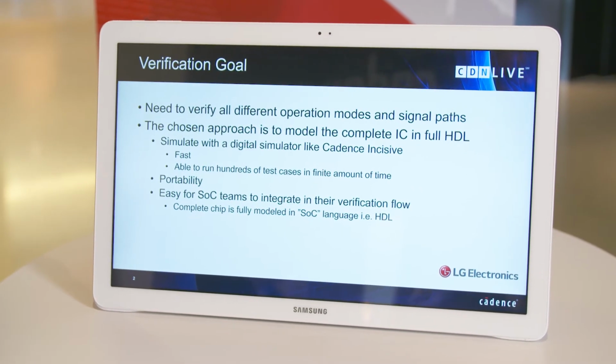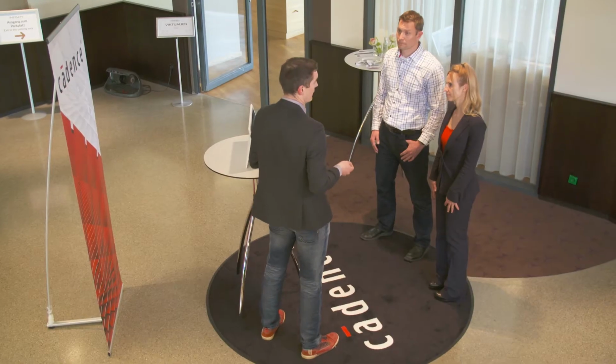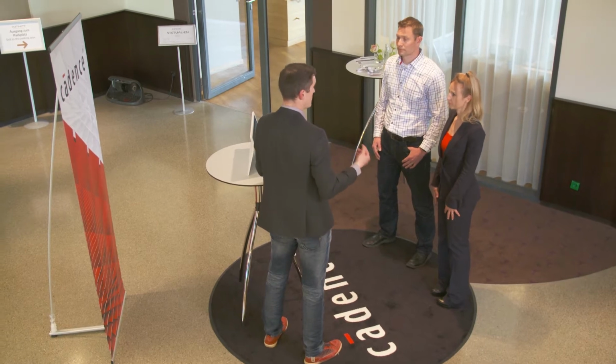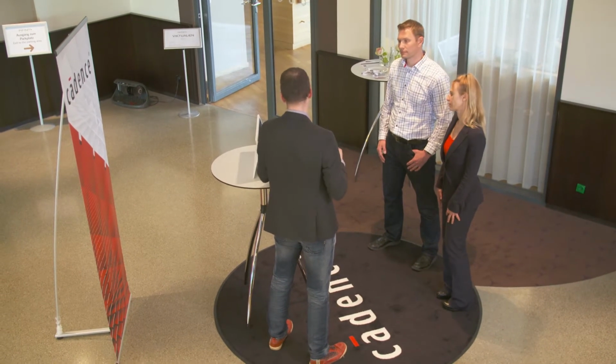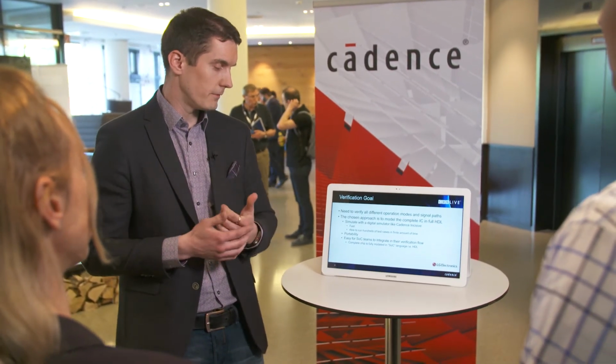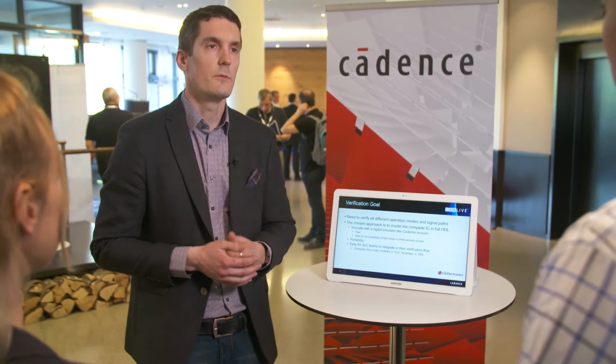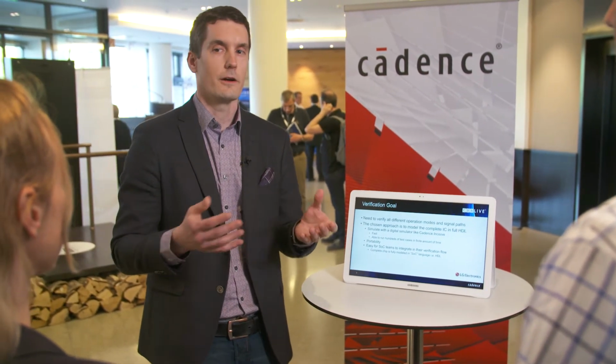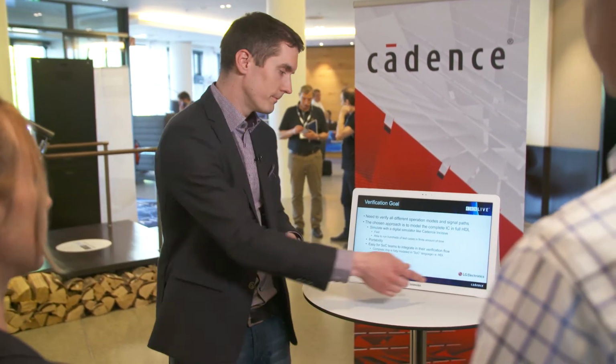And the chosen approach to do this is to model the complete IC in full HDL. This enables us to use a digital simulator like the Cadence Incisive, which gives us the speed, it's fast, it's portable, and we can actually hand over the RFIC, which is essentially analog, to the SoC team for their integration and verification purposes.